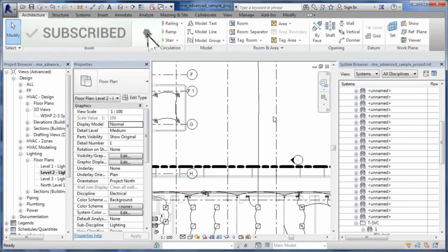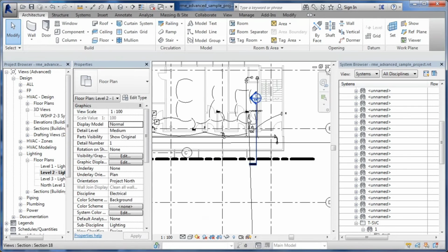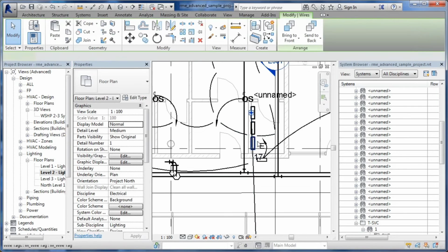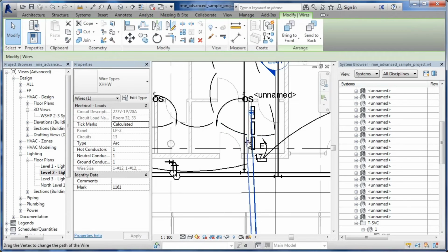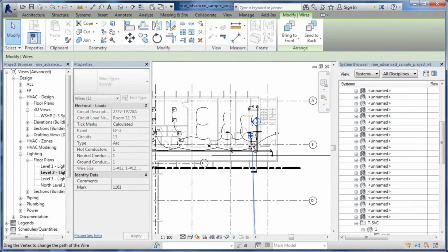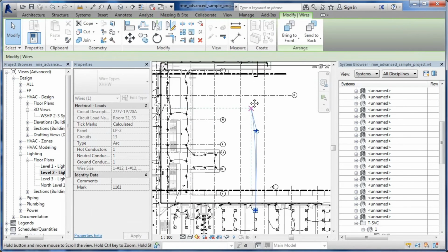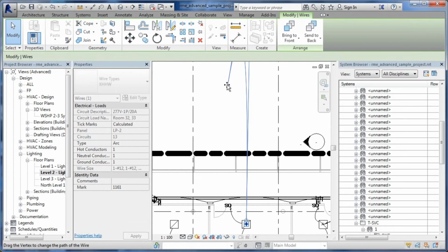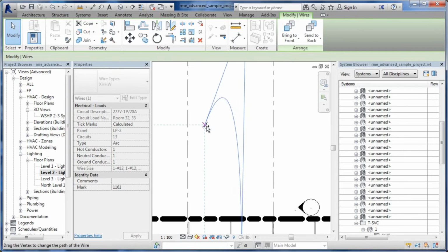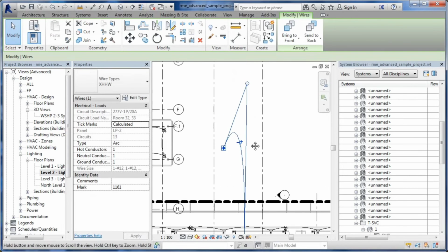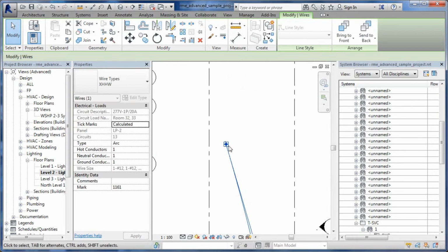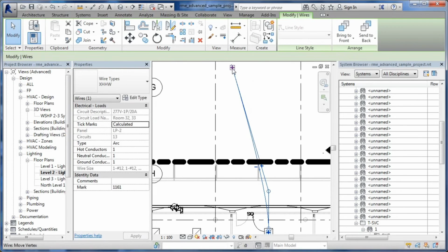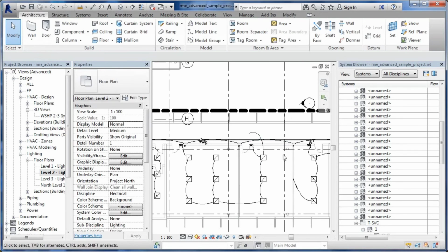Okay, and this has a huge home run on it. You need to pull that guy back a little bit. Pick on here, grab this connector. I'm going to use my middle mouse button while I hold down on that connector and pan. So I'm using actually 2 fingers at once here. And I have to be careful because I have another node there. So I'm just going to pick there. Pull this guy down. Reconfiguring. I'm not sure if that's a bit of a bug or not. But fix that home run.